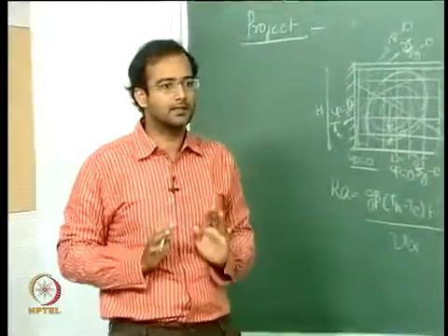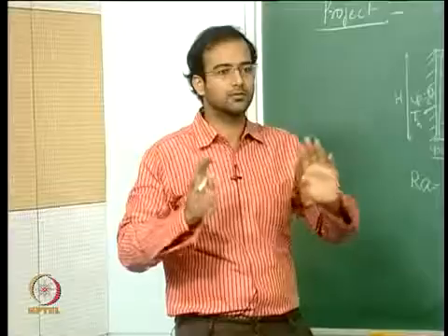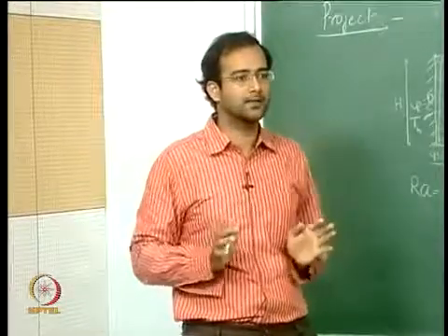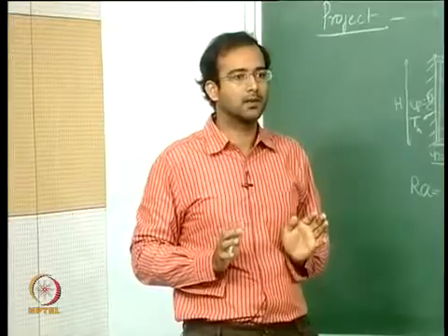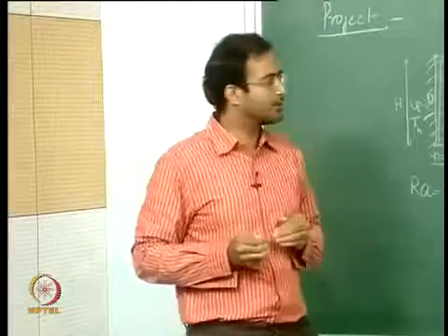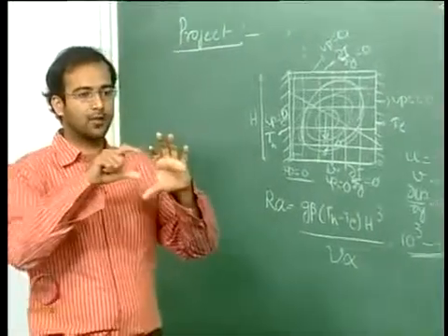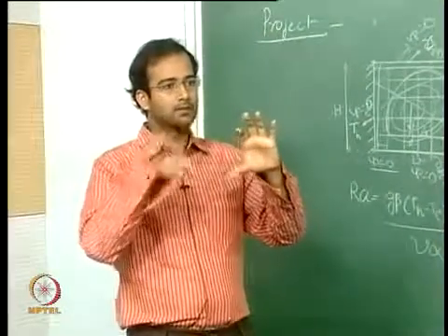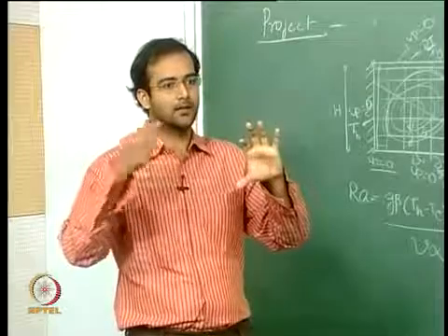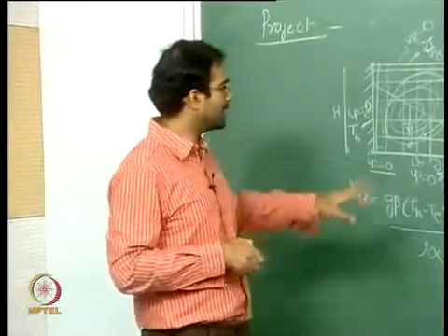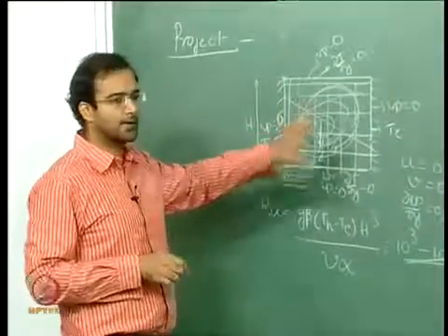Finally you get a resulting set of algebraic equations which you solve by any method, whether you consider this as a matrix and use inversion methods or do it iteratively. Here you can do a very iterative solution which is going to take only a few lines of code, do loops where you just iteratively keep doing it till the convergence criteria is satisfied, and then you can plot the results for streamlines.